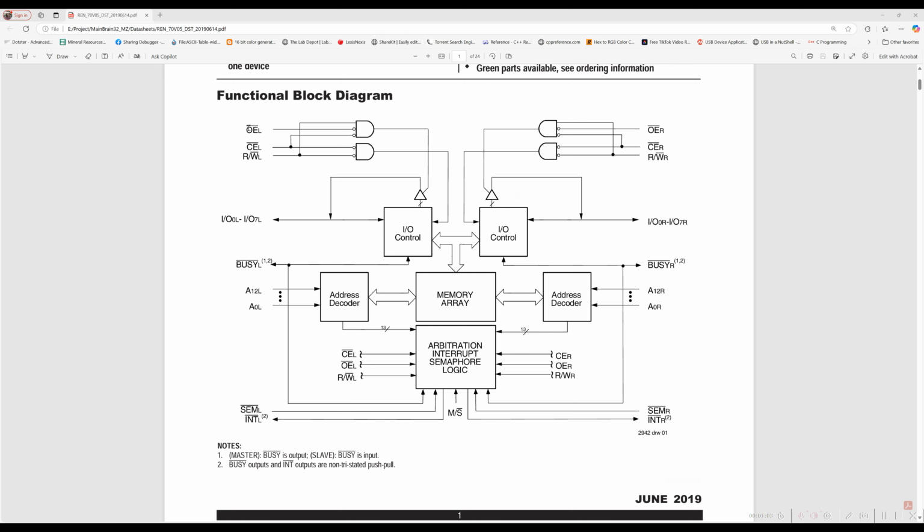Then the output enable, since it's low, is sending data out. All these 8 data pins are being driven by whatever's in the memory location. And if it's blank, it's probably FF hex, which is all high. So we're driving highs out, all right?